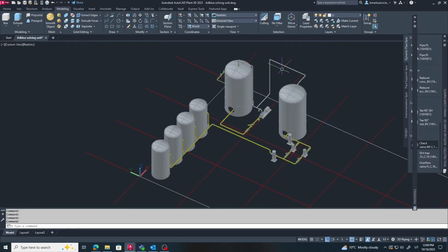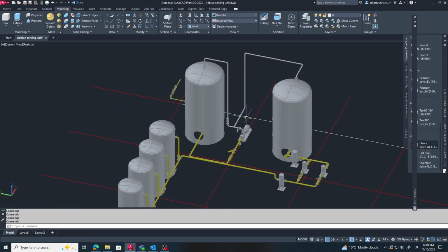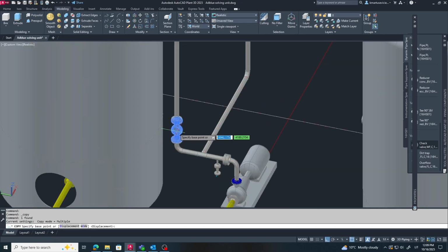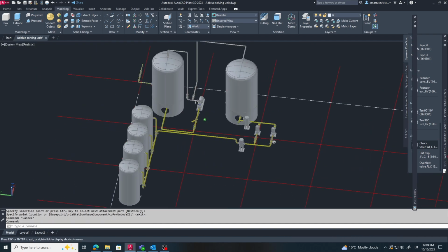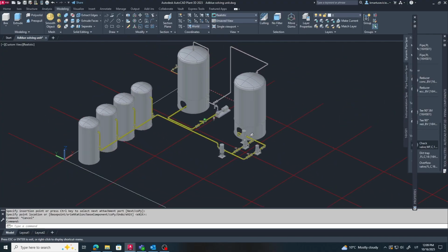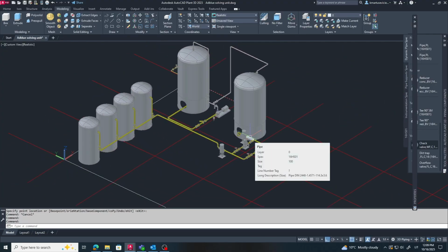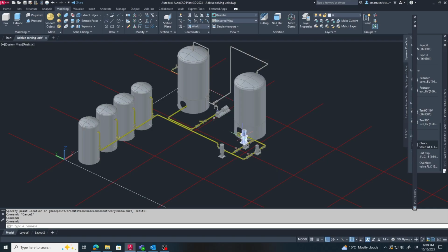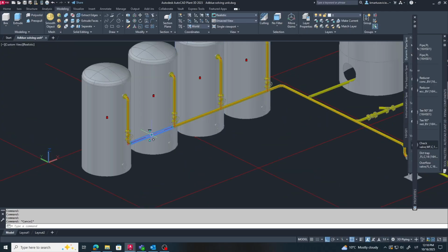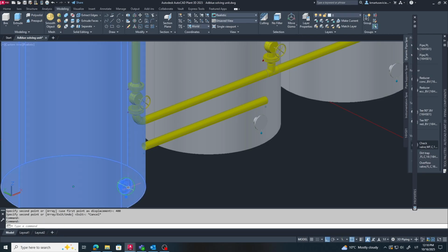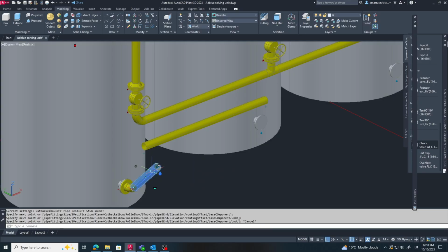Just one small fix in our water line, and then we'll get back to the collector line. We need to have the option to either recirculate the water or pump it into the reactor. These two valves make that possible. By switching them, we can easily choose the desired flow direction. I'm copying the pipe to keep the same coordinates, just placing it a little bit lower. Then we simply stretch it and connect it to the vessels the same way as before.